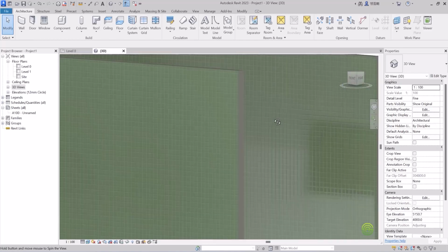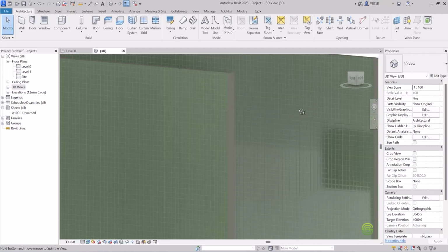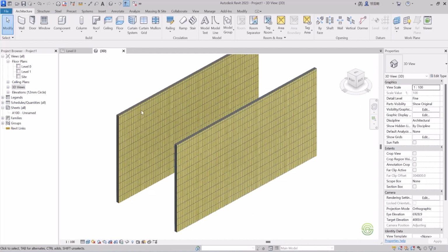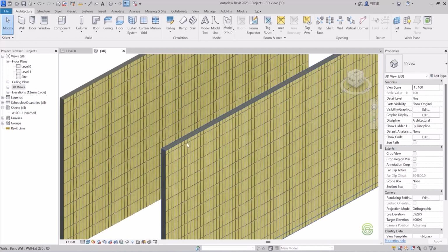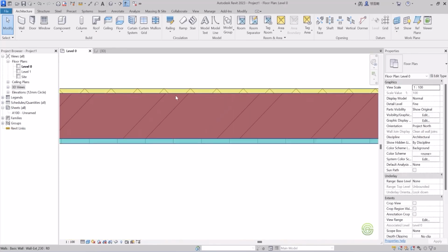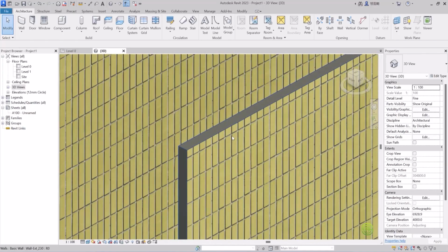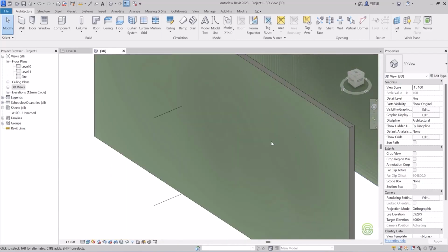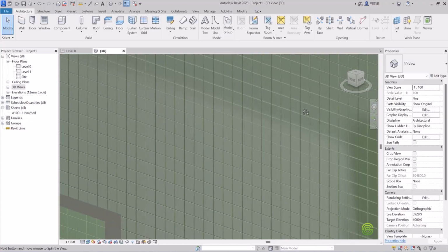You can also change the scaling of the interior material. So like this, we can add layers to the wall. Like we have added two layers in this wall. When you go to plan, we can see this is the main wall which we had before, and now we have added two layers at exterior and at interior. And after adding layers, we have also applied materials to the layers. Like this is the exterior material, and we have also given an interior material like this.